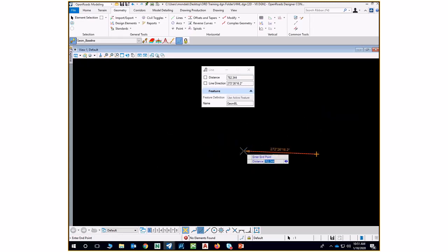So let's key in some distance like 750 meters. Now you can hit the Enter key. It will lock the distance, and then the right arrow key will go to the direction. Now you have locked your distance, so you are free to move with the same 750-meter distance. You can now set the direction. So let's say we'll set this direction as 280 degrees.